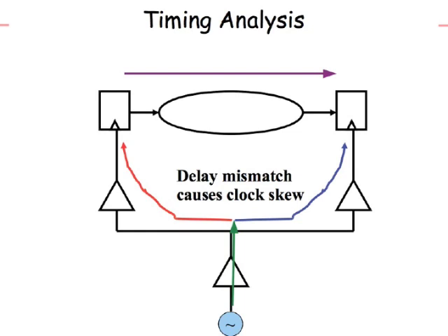So you use that to adjust the delays, just like how you do wheel balancing for the tire of your scooter or your car. You have to keep adjusting some weights here and there, so kind of like that is done. Of course, this is very complex to do by hand because the number of flops is just too large. So it's all done in an automated way by clock tree synthesis tools.